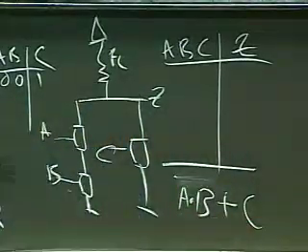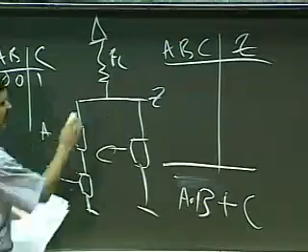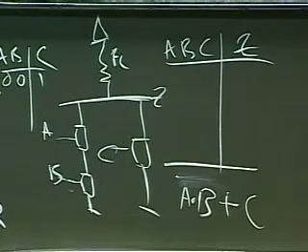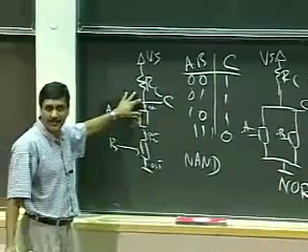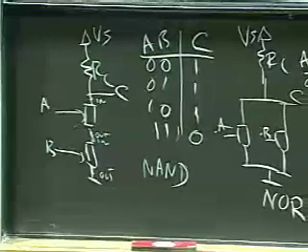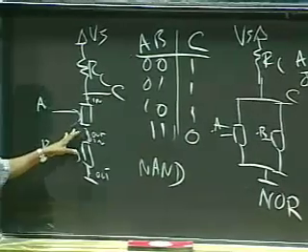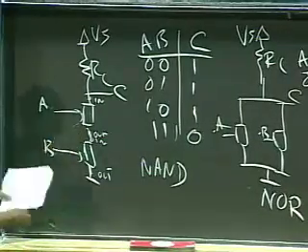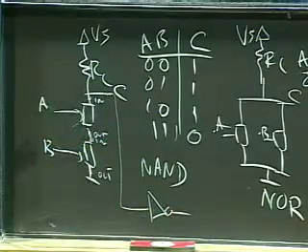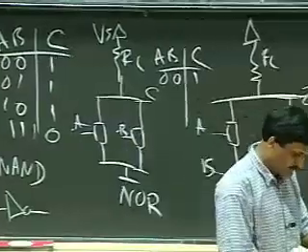And so because of that, I get something that looks like this. So this is my A dot B. This is my plus because of a parallel shunt here. And ultimately, this causes an inversion in this gate. So our primitive pattern has a generic inversion built into the output. That is why we commonly end up building NAND gates and NOR gates and so on as the simplest gates. We don't build AND gates and OR gates. How can I convert this one to an AND gate? Anybody? Put an inverter on the output. So what I can do is take this little sucker here, put an inverter here, and I get an AND gate. So the real primitives in circuits tend to be NANDs and NORs.